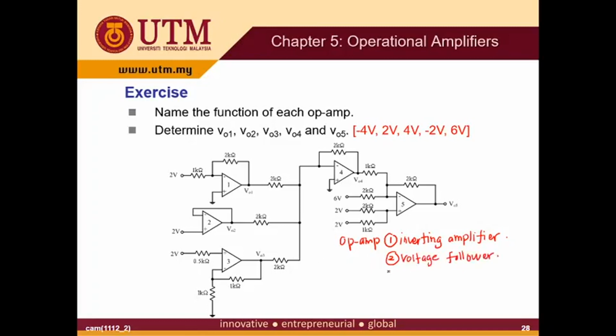Okay, number 3. The input is at the non-inverting input port, and we have the negative feedback here, and this is a single input, so this is a non-inverting amplifier. This is an amplifier, but the gain is positive.